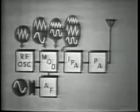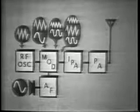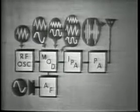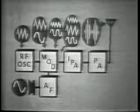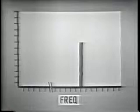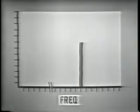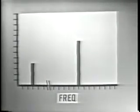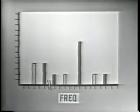The RF carrier and its sidebands are coupled through the RF tuned circuits to the antenna. So we transmit these three frequencies: the carrier, the upper and lower sidebands, in a composite waveform. Now let's review this composite waveform for just a moment. First, let's look at the frequency relationships. The carrier frequency determines the location in the spectrum of the transmitted signal. And when the carrier interacts with the audio, or the modulation frequency, the two sidebands are generated. Now, each sideband is spaced the distance of the audio frequency from the carrier.